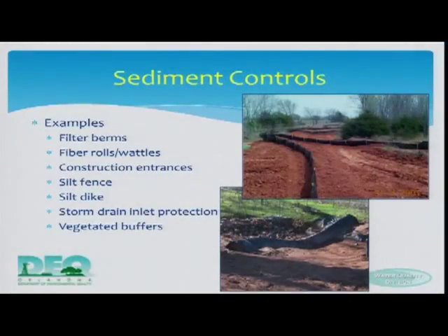We talked about velocity dissipation. This may look a little bit overkill there, but remember we talked about a rule of thumb for silt fences, about 1/3 of an acre. Once you get beyond that, it's kind of blitzing the silt fence. You're sending more to it than it can handle. But if you keep it at about 1/3 of an acre, it'll do a number for you. It'll really do a good job.